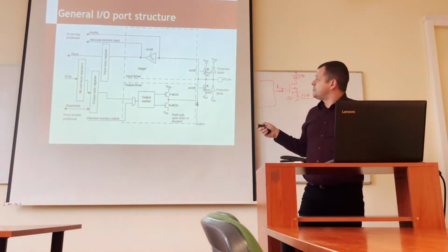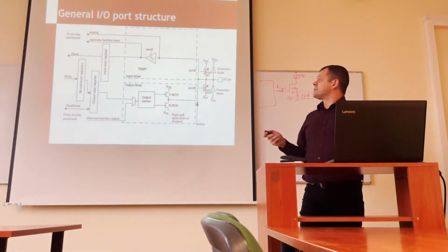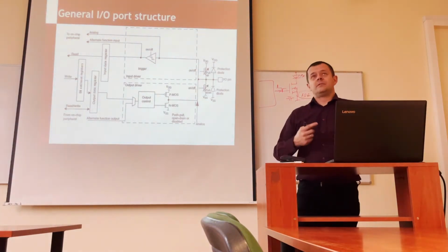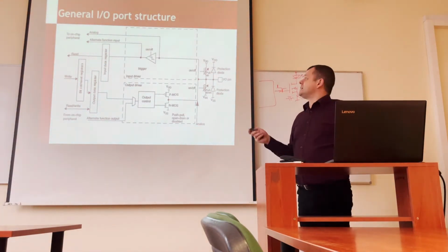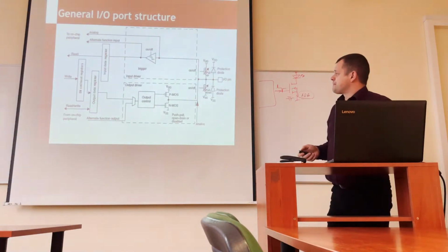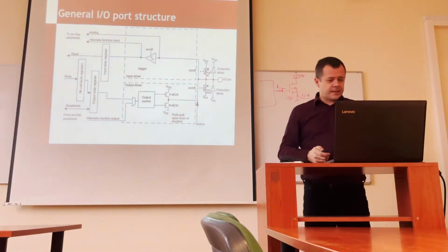Still, we have in some microcontrollers special analog inputs. Of course, the analog input is connected directly to the I/O pin. Then, if we want to use analog input, this buffer is simply put in the off state and in high impedance so that it does not disturb the analog functionality. Analog may be an analog to digital converter, maybe an op-amp, maybe an analog comparator. So this kind of functionality we can find connected here. Yeah, I think that's it.